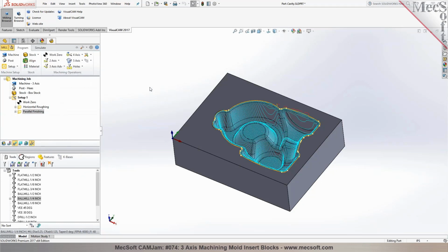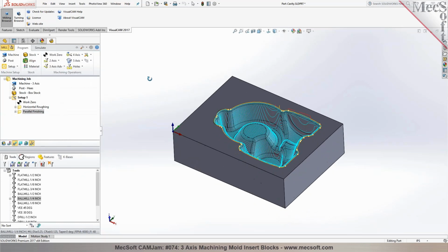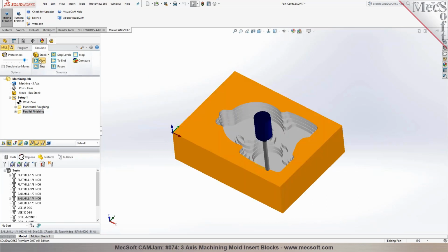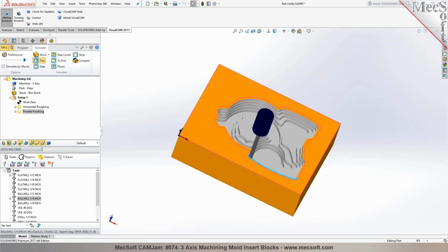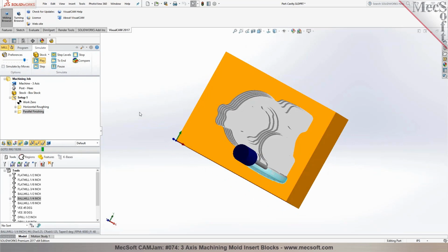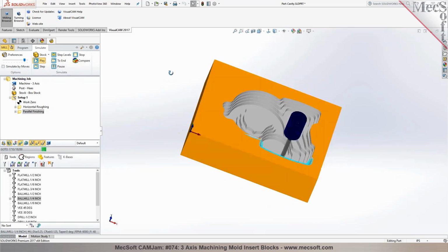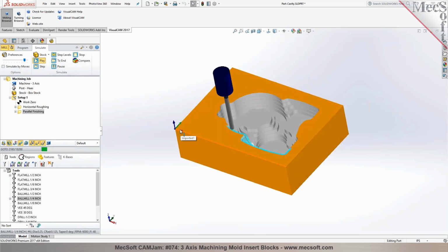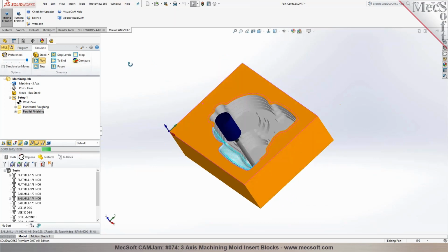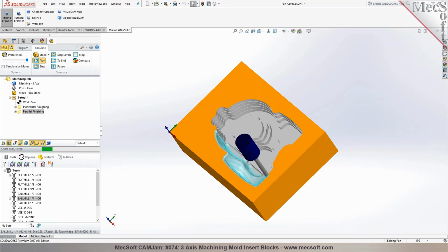So in this particular step, you have a pre-finishing toolpath or a finishing toolpath. This is called parallel finishing, which basically follows in parallel planes following the 3D model. The angle of cut is set to 0, which basically runs parallel to your x-axis, following the model back and forth. Now with the Pro configuration, you have more options for programming 3-axis toolpaths.